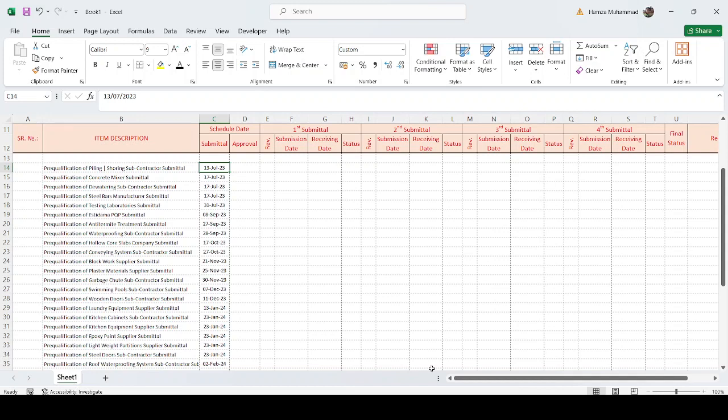In the project specification, there's an item named project submittals and approvals. In this submittals and approval specification, go and read it. You will find how many days are mentioned for the engineer to review and approve the submittals. Sometimes it is very specifically mentioned that the engineer requires 21 working days to approve the submittal, or sometimes it is not mentioned. If it is mentioned in the specification, it is very good. If not, then we have to check with the engineer how many days he wants for the submittal. Normally here we assume 14 days.